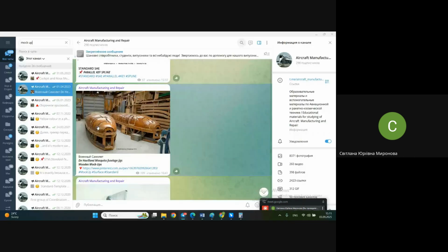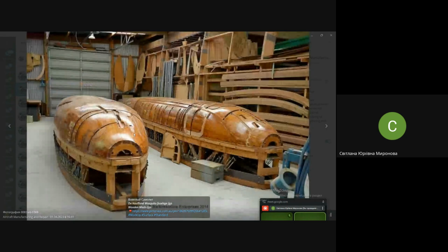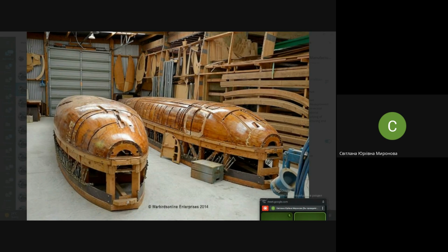That one is not a surface standard, it's a mounting standard, it's frame-like, and that one also was frame-like. Something like this is what a surface standard looks like, but that one is not even a surface standard. Because a surface standard will have a completely solid, streamlined surface, without any scratches, without any dimples, only some drawn lines maybe.